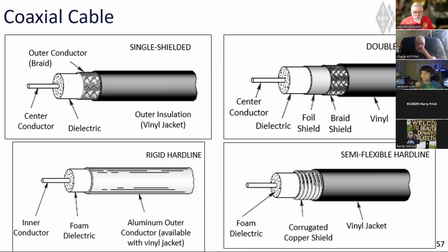And here is a picture of coaxial cable. And you could see why you would call it a center conductor, being as it's round. And some of the very expensive stuff that they use on high power transmission, like at TV stations, will be a pipe with air around some kind of a solid conductor that's in the middle of it.